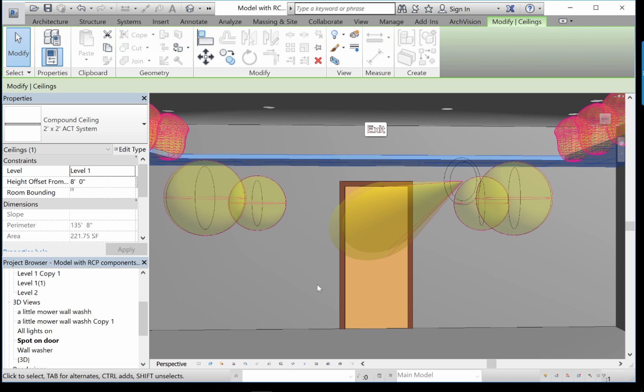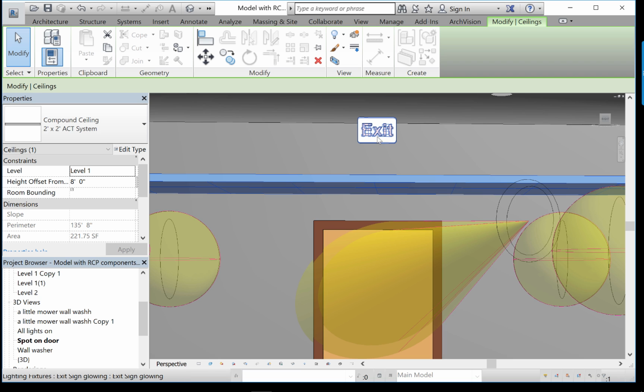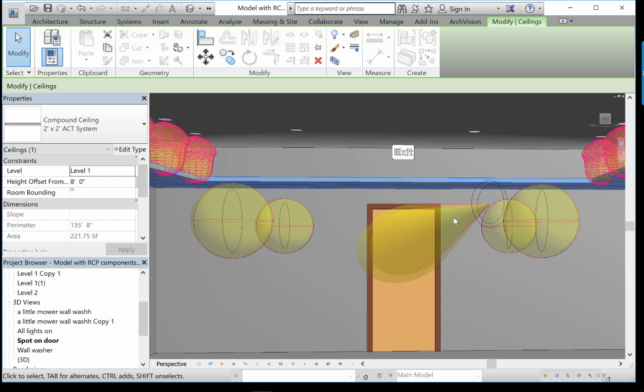Even, say, a niche, like a recessed niche, you could try to paint the top of that arch or divide the surface and paint just a small piece of it, and you could mimic niche lighting pretty effectively. Again, these are hard things to do and to get at the view where you can paint it. The other thing is making an exit sign that actually lights up is always an annoyance in my mind. They don't by default light up, but you can paint the EXIT letters with a unique color, or if it's set up that way, you can actually configure the parameters of that.